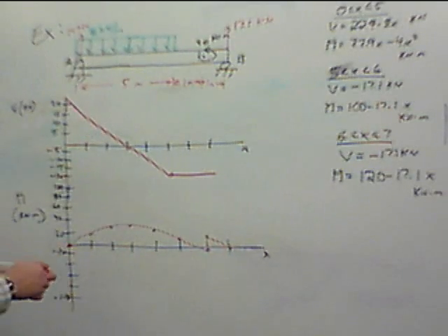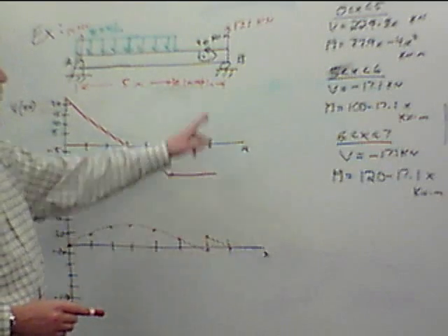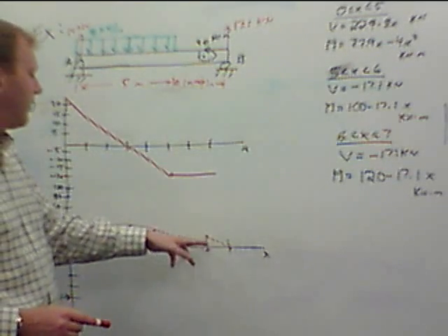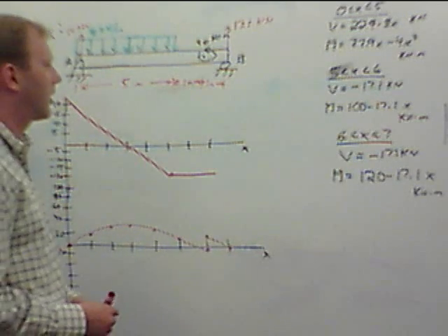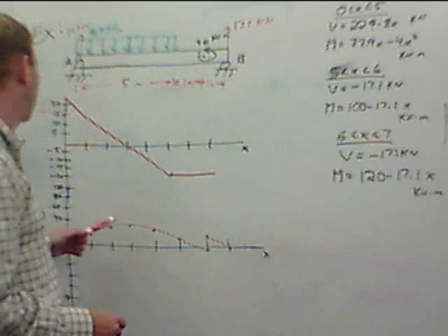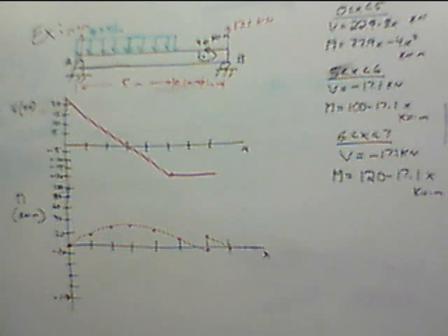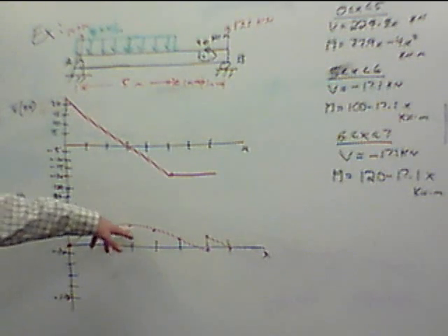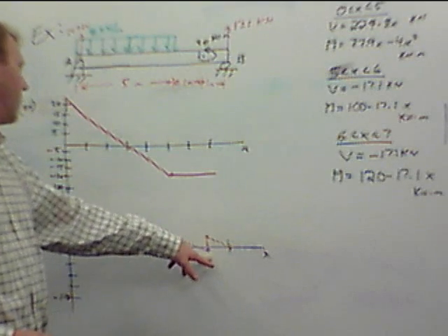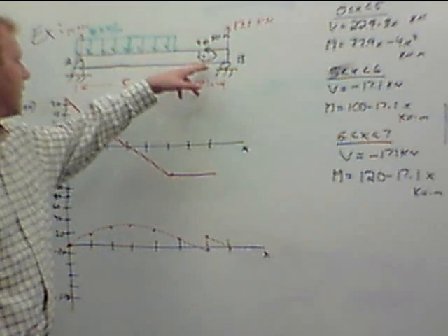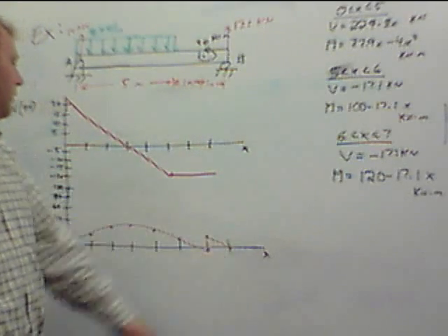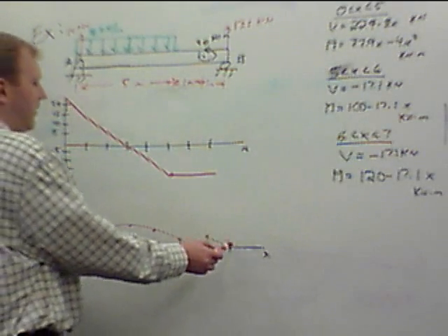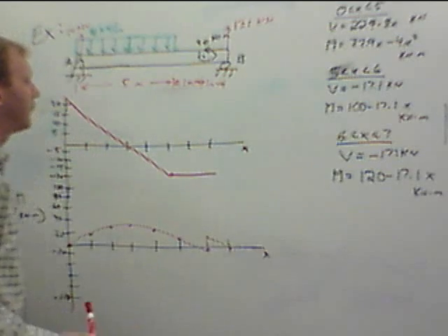Worth noting here, we have this discontinuity at 20 where we have an applied moment. Again, the scale got a little scrunched because I miscalculated the range on this, but it does show you the moment diagram here as we go from 20 up to the low 30s, back down to slight negative just before we get to this applied moment, but then the applied moment causes it to go back positive. At the end, we end up back at 0.